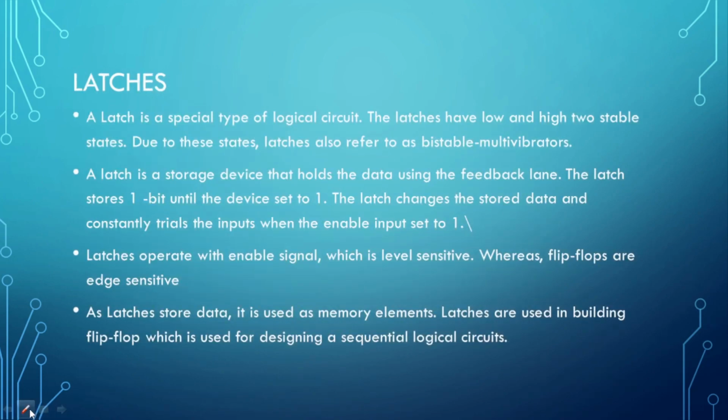A latch is also a building block element in digital circuits and it is a special type of logic circuit. It also has two states, a low and a high stable state. For this reason, latches are also referred to as bistable multivibrators. Latches operate as level triggered digital circuits and flip-flops are edge triggered.